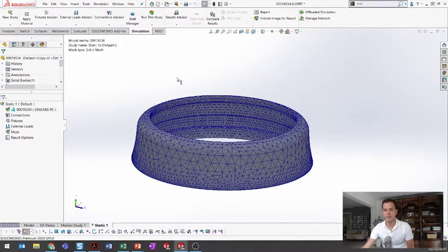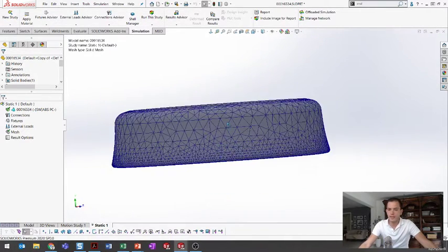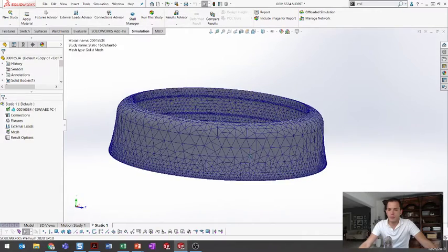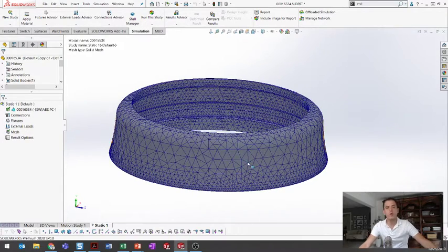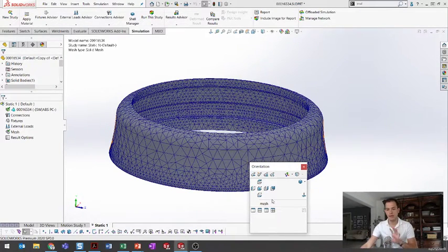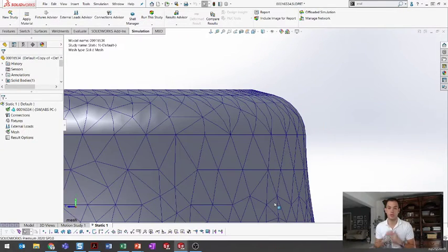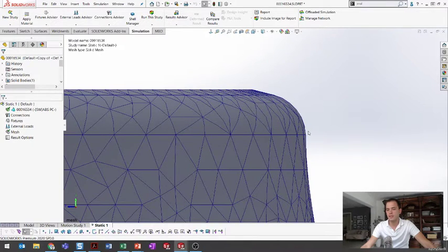Okay, so here, let's talk only about meshing the geometry. Now that I have a high quality mesh here, a curvature element, you'll see that it's able to map to this geometry. If you look here, my mouse I have over the fillet, you can see how these elements are able to curve. You can even see that mid-side node in this particular element.